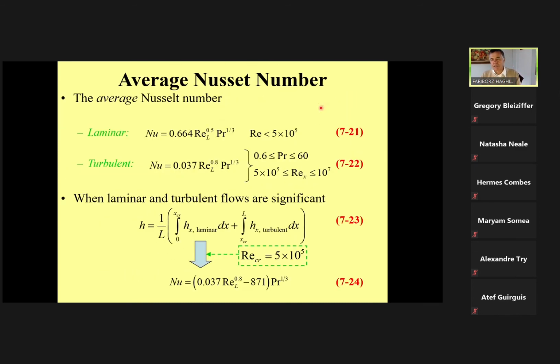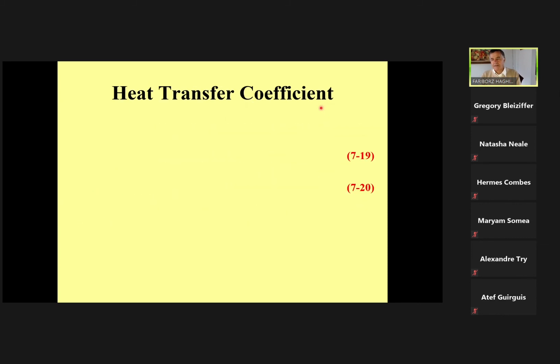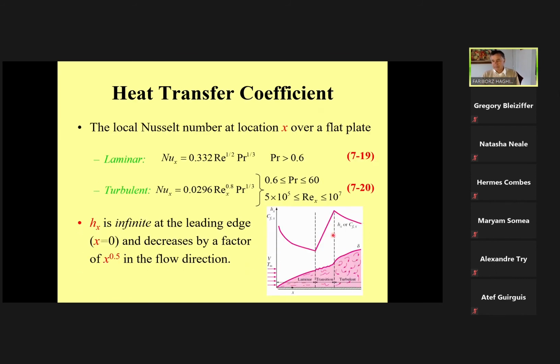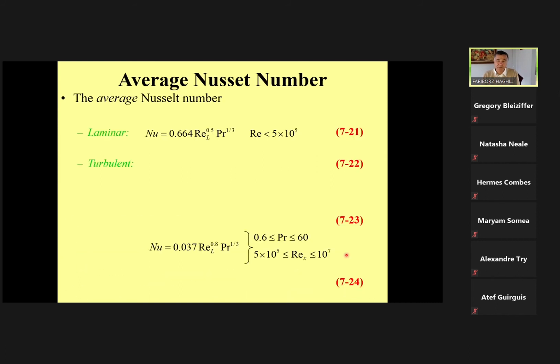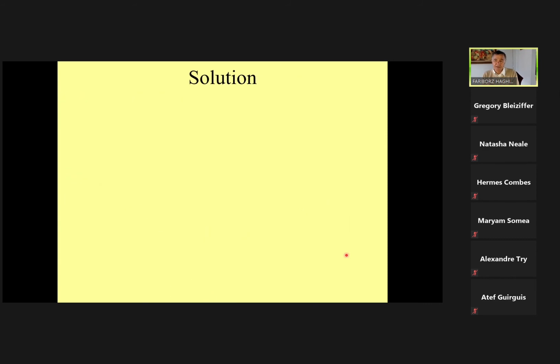In general, let's look at here. You have convection and at the same time, in parallel, you have conduction. You have convection here and you also have conduction here. But the contribution of convection is 10,000 times more than conduction. Therefore, you can ignore the conduction component. It's parallel conduction and convection together. Okay, that's the meaning of that.